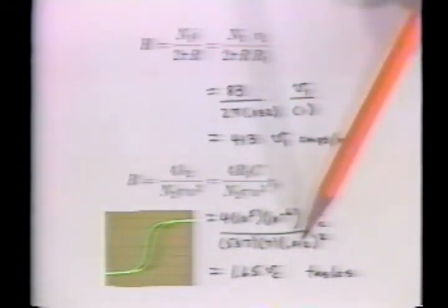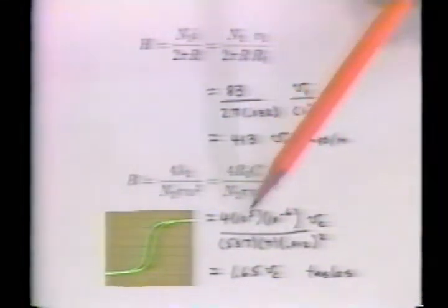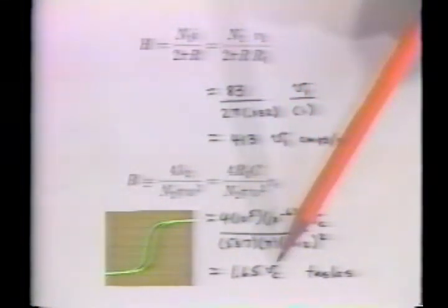Polycrystalline ferromagnetic material at the domain level has randomly oriented magnetic moments that tend to cancel in the absence of an applied field. As a magnetic field is applied, the domain walls shift. Those domains with magnetic dipole moments aligned with the applied field grow at the expense of domains having oppositely directed magnetic dipole moments. The result is a net magnetization that tends to be in the direction of H. In ideal materials at high magnetic fields, saturation results when all of the domains combine into one. In real materials used for transformers, imperfections and boundaries result in the domain walls encountering a resistance to motion. A phase lag then develops between the magnetization and the magnetic field intensity H.